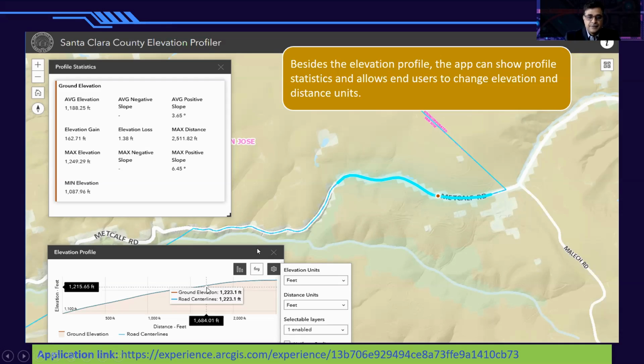So the idea is you could go back to this application, and let's say you figure this out, this is the part that you want to really narrow down. You could go back to this application and this time draw a profile around it, just a polygon around it, and say, okay, this is the area I want to select. Then the software will give you this option, but it's only going to give it for that small portion, where you'll be able to figure out, okay, that is my steepest grade and this is the percentage, and then can our vehicle operate here or not.